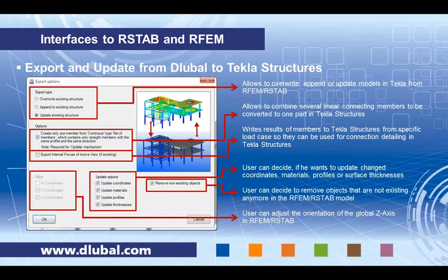from Dlubal software. For example, you can analyze frame by frame and then individually update your Tekla model with each new frame. Or you can have one building and add another building if you work in a 3D environment in the Tekla model at the same time. The most interesting but also the most difficult part is the update existing structure feature. This will merge a changed Dlubal model with an existing Tekla model.